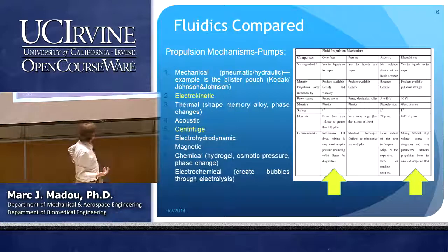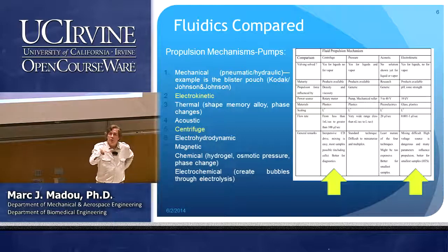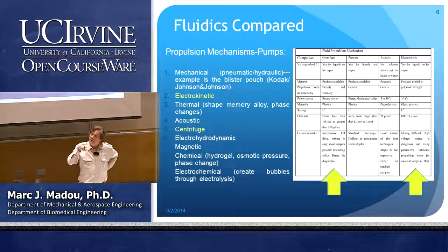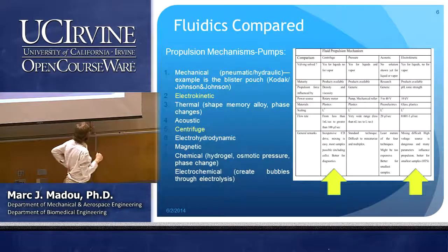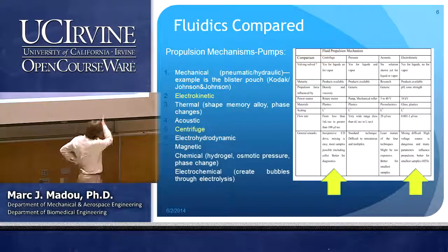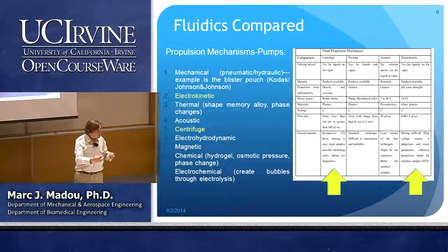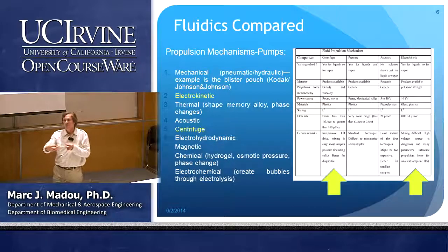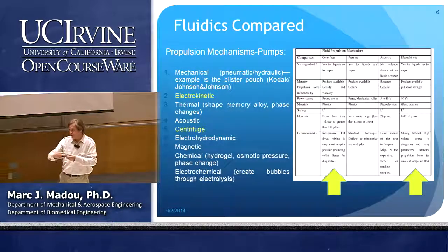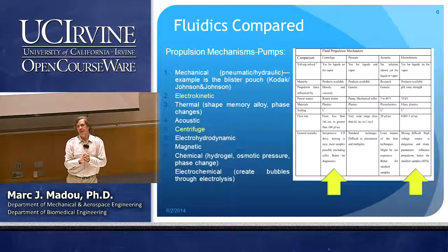Pressure is your regular pump. Next, acoustic, that is basically by sending acoustic waves over a thin plate and have these acoustic waves unidirectional so that the liquid follows the acoustic waves. It's a technique pioneered by a friend of mine, Professor Dick White at UC Berkeley. And then the last column, electrokinetic, that's the one you were referring to. That's electroosmosis, where basically you apply a charge, a voltage, a DC bias across a capillary, and you will have osmotic pumping enabled that way.